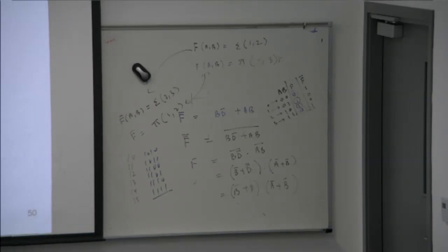Got it? Can you see WXYZ? So what are the don't cares? The don't cares are 10, 11, 12, 13, 14, and 15. And you look at all the previous answers. Can you see? 1, 10, 6. Got it? Yes. Now, the 3 variable Karnaugh map is ABC, and this is a 4 variable Karnaugh map WXYZ.